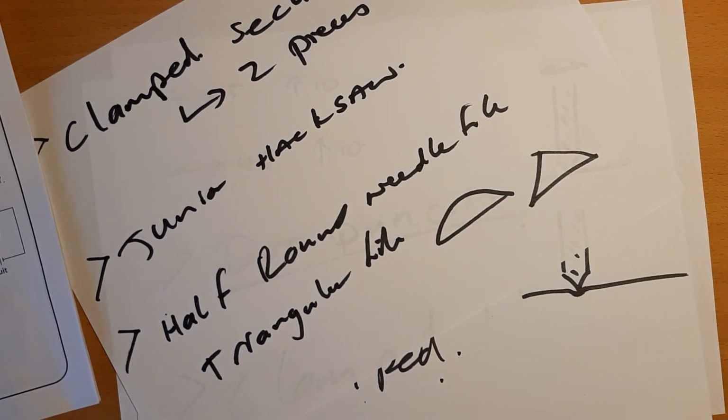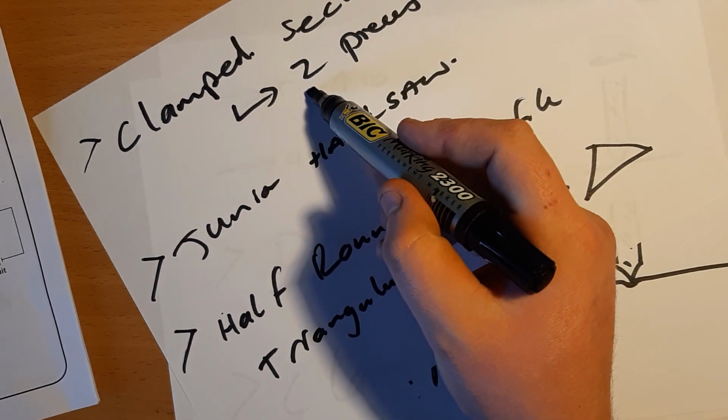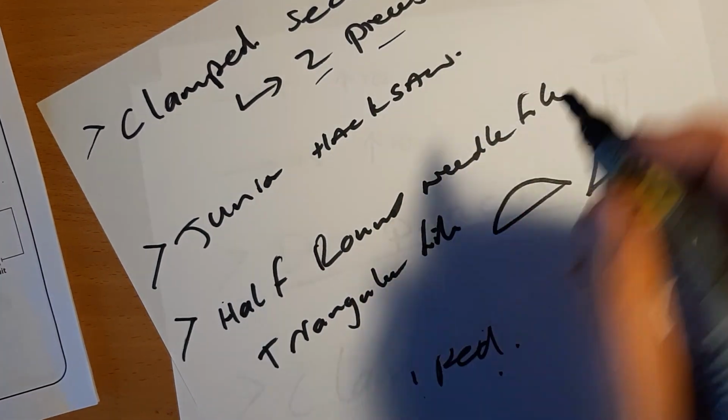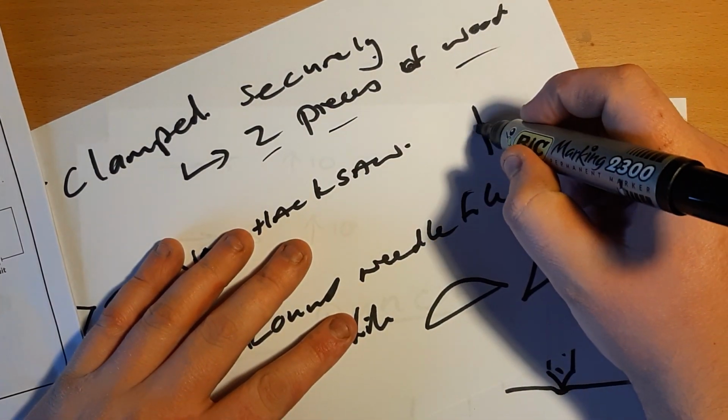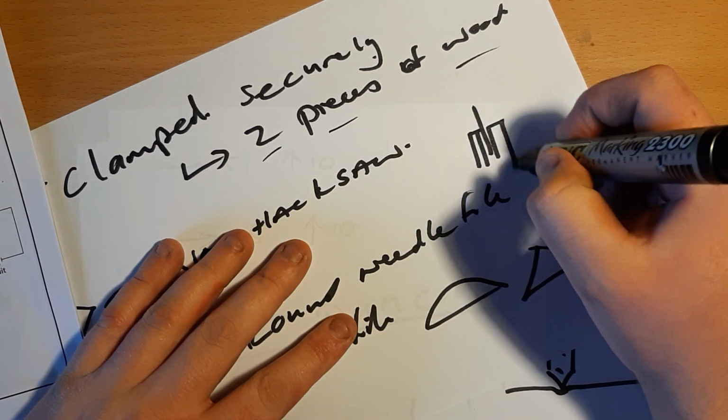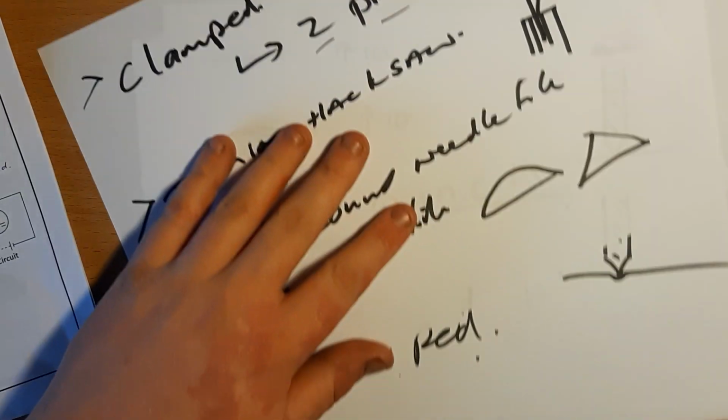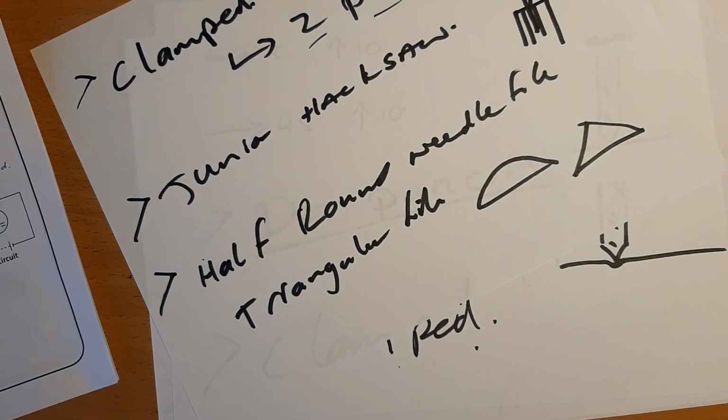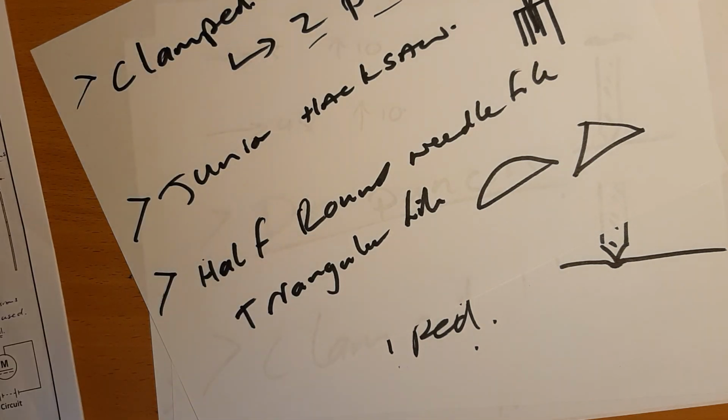The other one, if you're filing it, and as I said up here, if it's not clamped with 2 pieces of wood, the piece is just going to be in the vise like this. That's the vise holding it there. What happens is it's just going to bend. That's to prevent damage to the piece. Another thing is large pieces can be awkward to carry and can be sore in the hands, if you want to be very pernickety about it. But that's your safety precautions there.